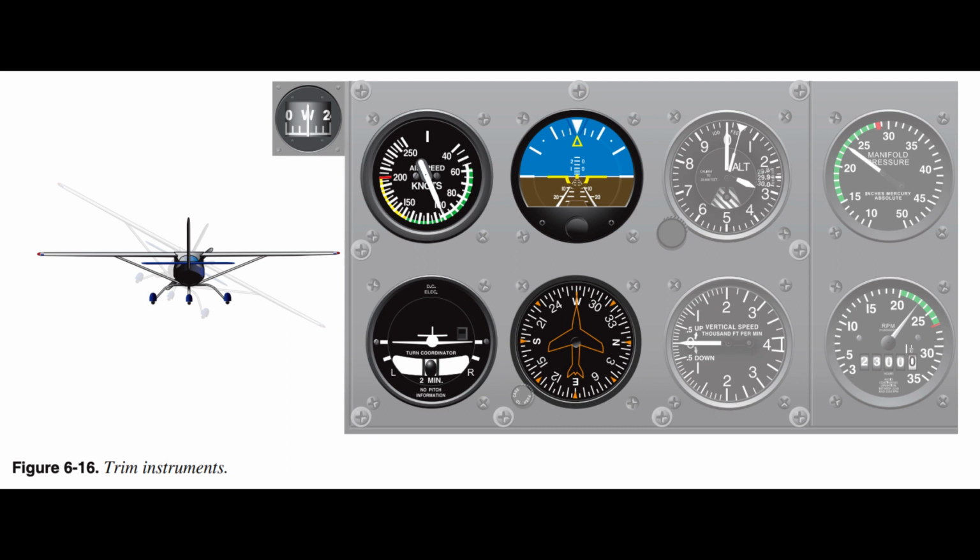Adjust the pitch attitude as airspeed changes to maintain desired attitude for the maneuver being executed. The bank must be adjusted to maintain a desired rate of turn, and the pedals must be used to maintain coordinated flight. Trim must be adjusted as control pressures indicate a change is needed.